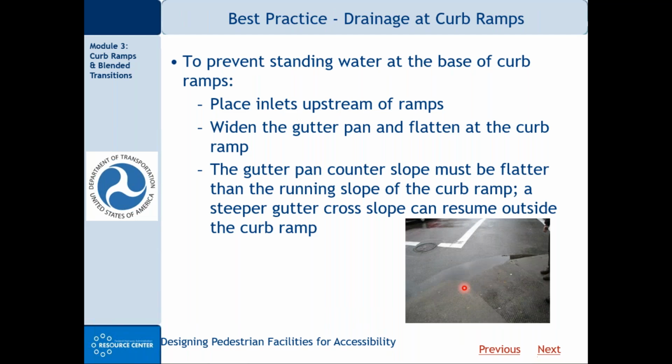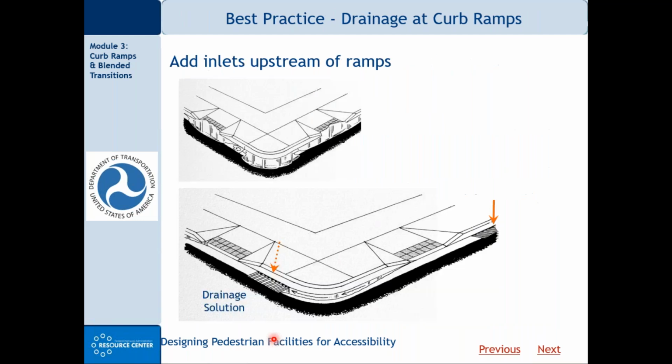Drainage, you saw this in the video. It is a continuing challenge. In many communities where I visit for training, you do see ramps with water at the base, or at this time of year, that may freeze and become ice and then be a slip and fall issue for pedestrians. Of course, the textbook solution is put the inlets upstream of the ramps, but I appreciate in reality we can't always do that, but we should try to pay attention to drainage.